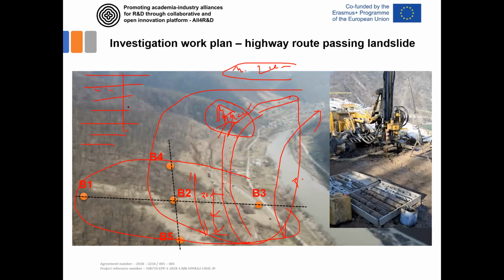Here you cannot miss a lot, but in this kind of conditions with deep excavation, with landslides, you always need to have this cross section. You always need to have this. And that's why I think that what is defined as minimum in this design code is only a minimum.